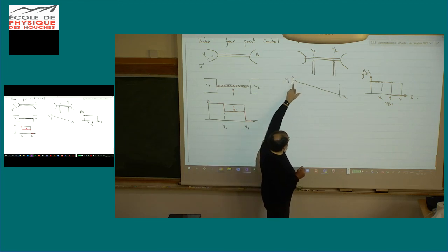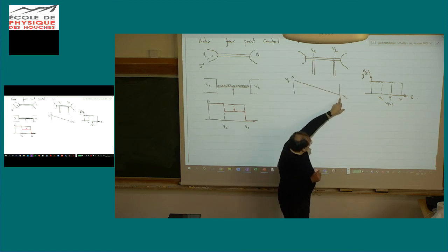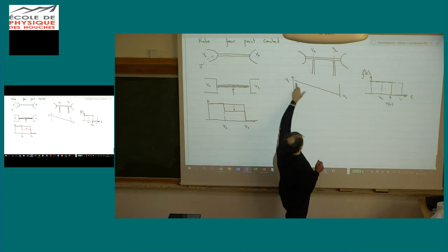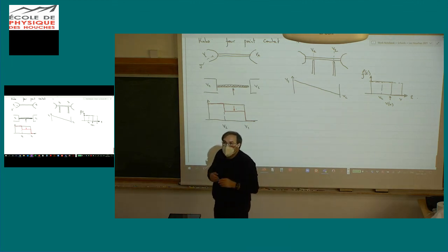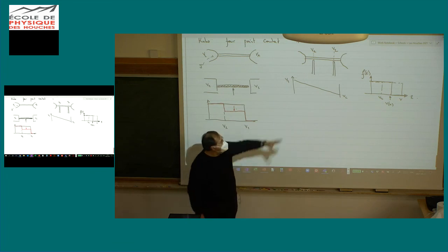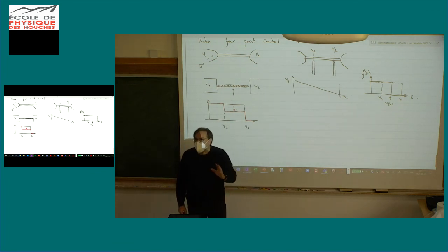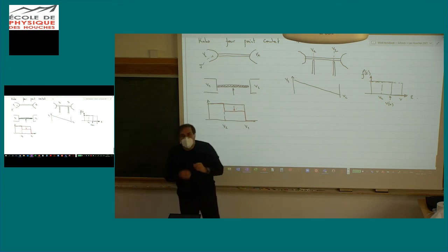You will have first a drop at the contact, then you will have something more complicated, then you will have a drop at the other contact. This is also assuming that you have Ohm's law, essentially that the voltage drop is perfectly linear, which is not the case if you have localization or more violent insulators. So very often this picture is simply wrong. Other questions or comments?